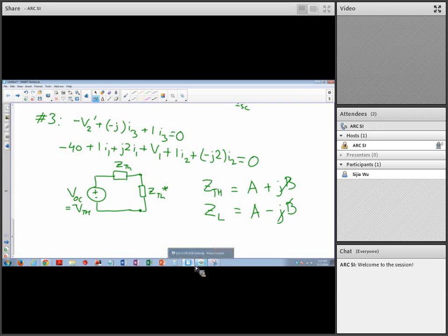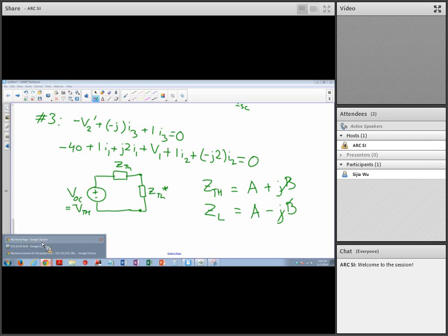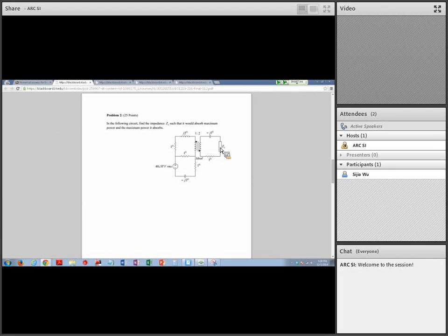The easier way to do it is the one he showed in class. The source transformation. I think that was after you flip it, then that's when you find the Thevenin's equivalent, and then you have to flip it back. For the way he did it, if you move everything to the right, you don't have to flip anything. If you move everything to the right, you haven't changed ZL, transformed it in any way. But if you choose to move ZL to the left,